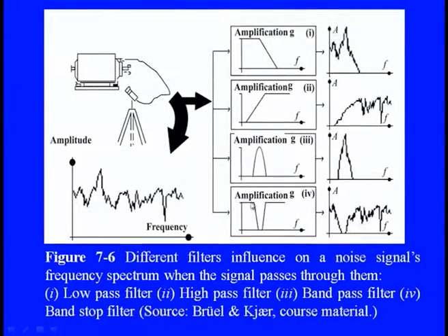Now, if you look at the nature of the band stop filter, the band which we defined can straightaway stop this frequency component. If you look at the real signature of the vibration, the nature itself says that this peak is now absolutely omitted, and the entire spectrum varies with whatever the required features are.